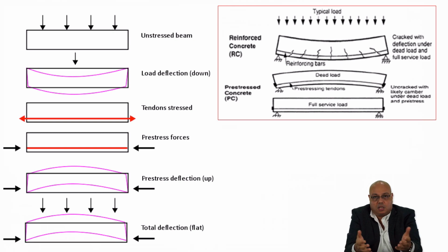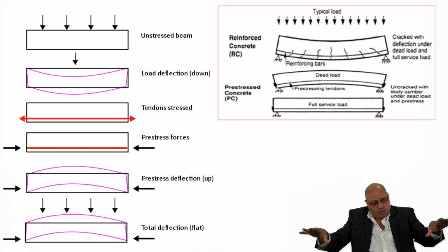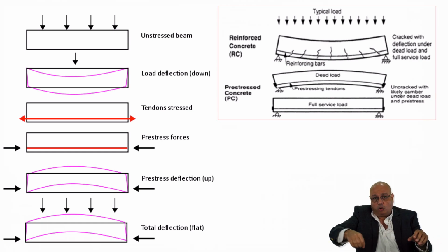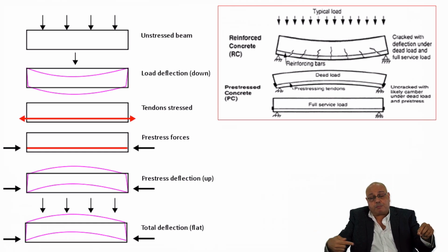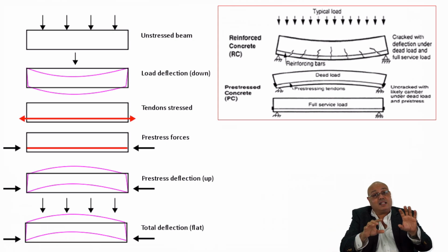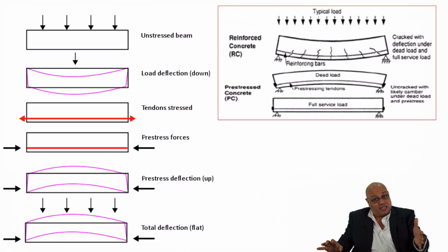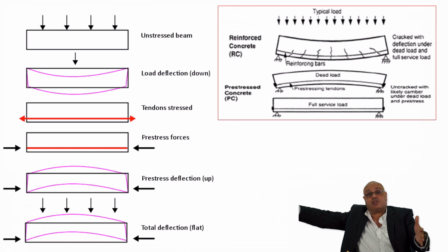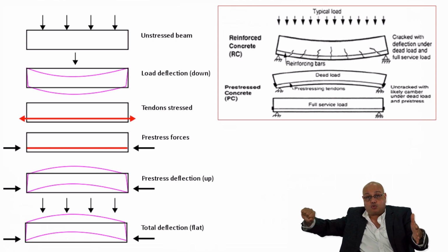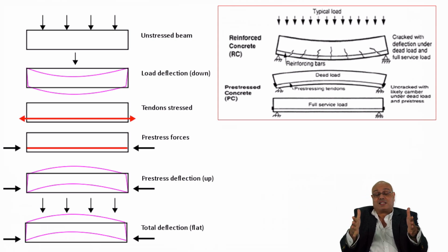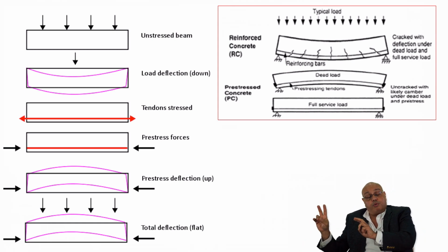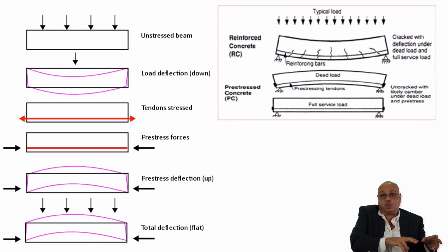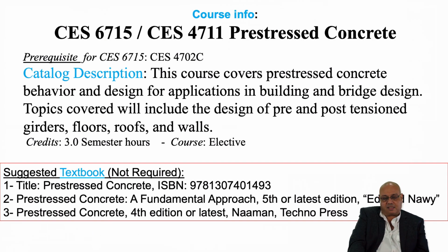That is pre-tensioning. The other one is casting the concrete with a tube, a hole inside it, and then inserting the pre-stressing strands inside the hardened concrete and locking it at one position, and with a jack stretching it from the other side. When you stretch it, you apply compression force to the beam. That is post-tensioning. Some of them are for precast applications, the others are more suitable for on-site, like segmental bridges and other applications as well. So we are going to be discussing them.